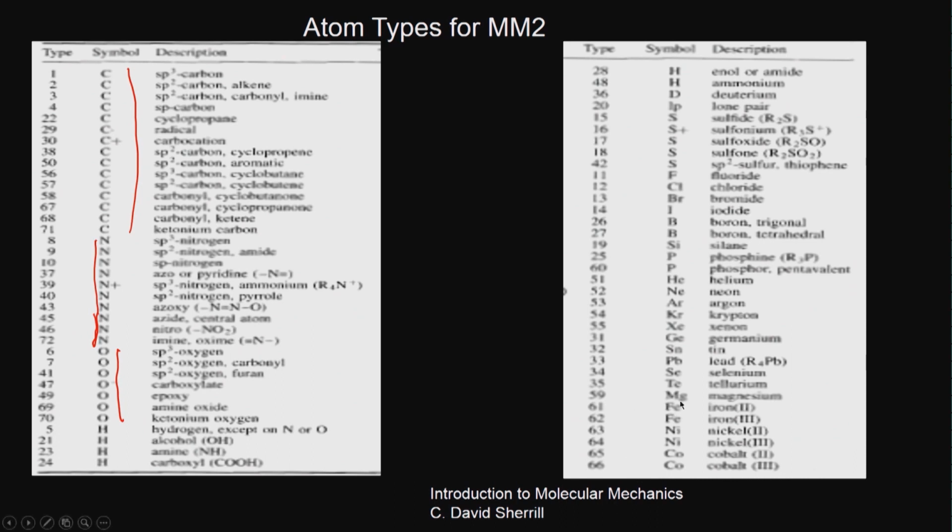But if you have some other metal, obviously it cannot handle, you may have to go for some other force field which can handle that particular metal, like for example, platinum maybe, that is not in this list. Sometimes some software will assume some other similar group metal and replace it with what they have. So each of these force fields will have a different set of atom types, so different parameter values. So it is always good to use only one force field for all your calculations.